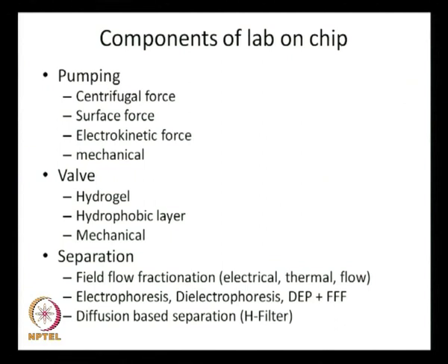Similarly, you can have surface force. How would that force look like? You have all studied capillary rise. If you dip a glass capillary inside water, there would be a rise of water through the capillary. How does it happen? The liquid has a weight, but that weight is balanced by the surface tension force, because glass is hydrophilic. So, surface tension can raise water through a certain height.